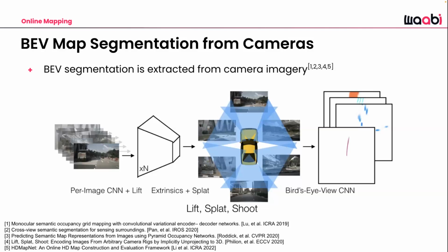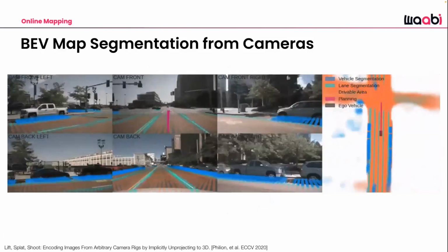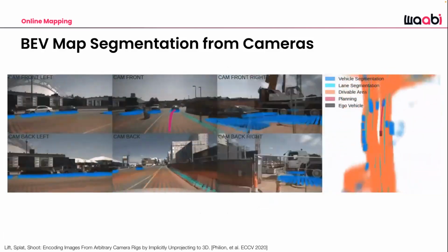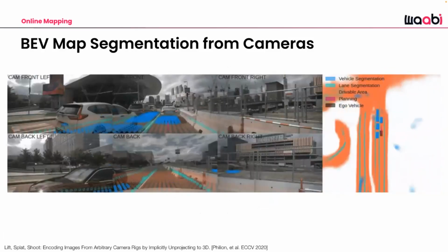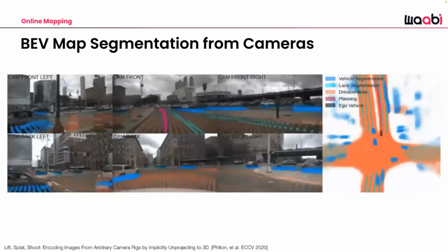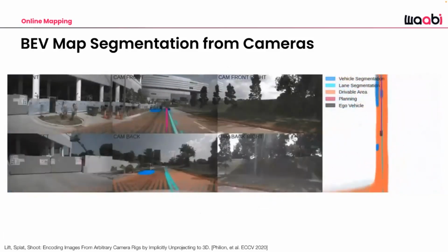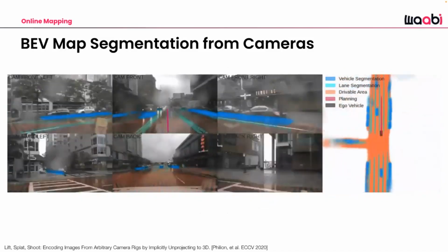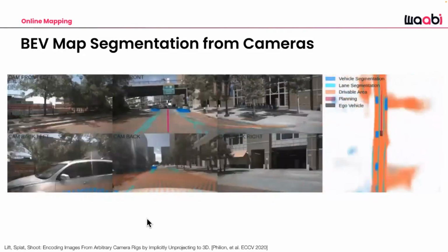And then in the splatting stage, you fuse all of these uncertain features using a point pillars architecture to convert them into this top-down bird's eye view segmentation that includes the lanes, drivable areas, and other stuff you might be interested in when doing driving. And this means that you can produce outputs like this, which look pretty good, and they jointly reason about the map itself as well as about the dynamic objects that you see in the environment. And it processes 6 cameras at the same time.